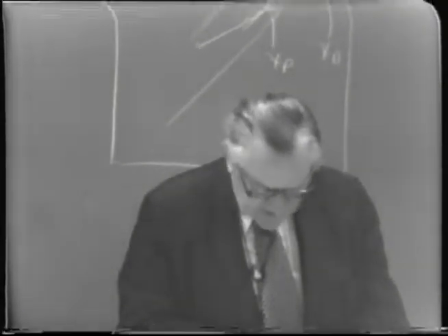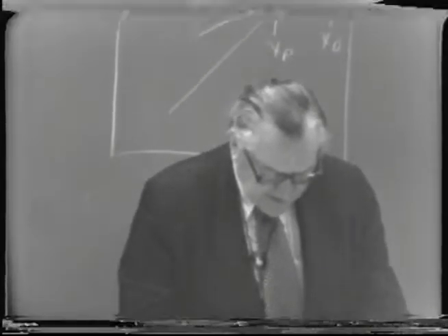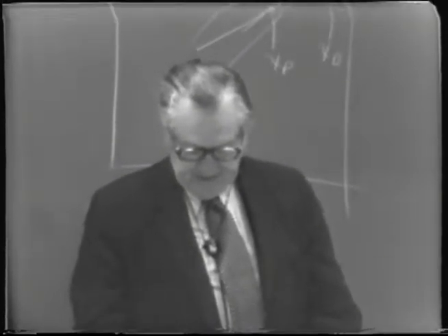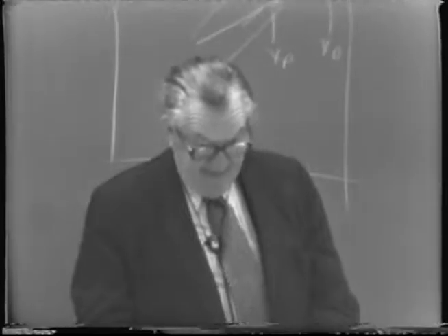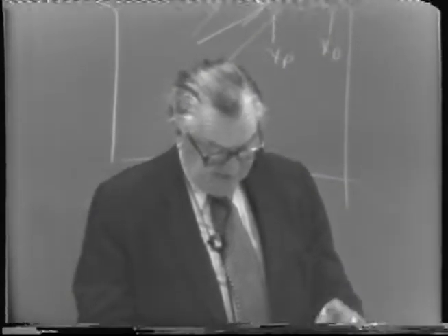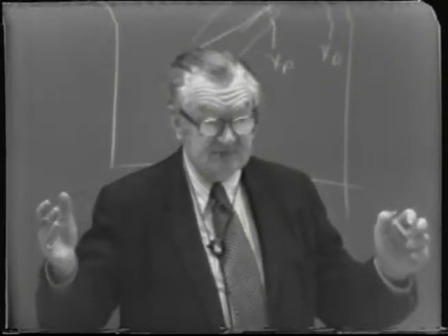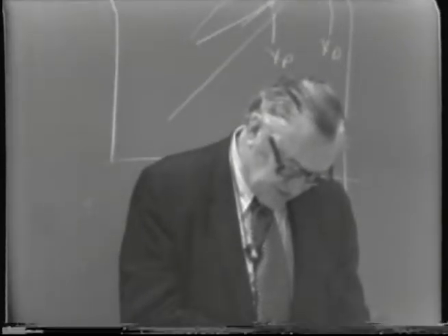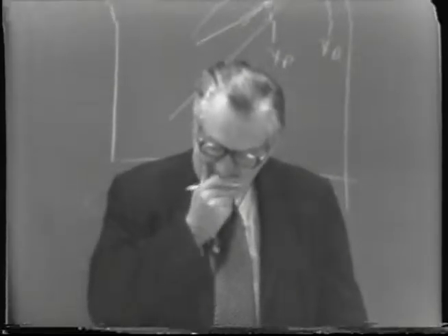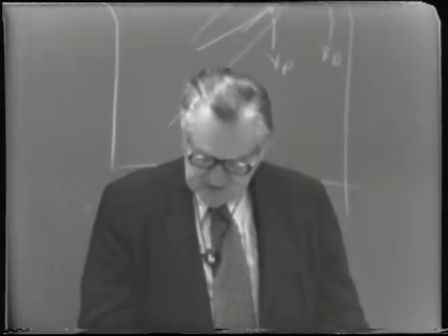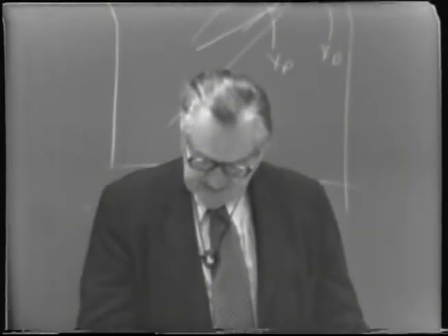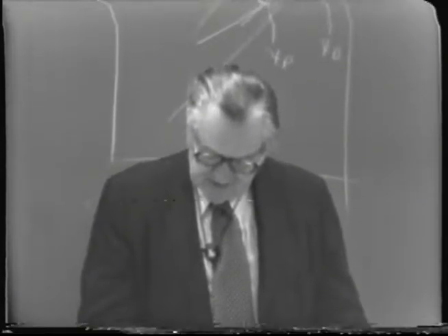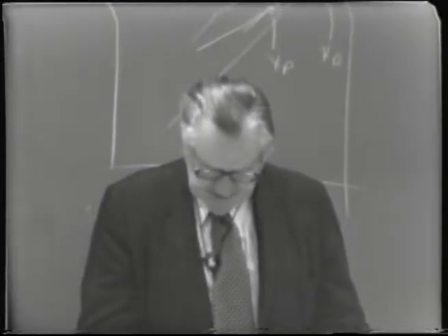So it looks like we required a total of just slightly more than 13 to span the change in liquid composition down to X sub F, or down to the intersection of the Q line with the operating line. Over on the right-hand side of this chart, I've written the number of ideal plates in the concentrating section. Above the side stream it's essentially 4, and below the side stream it's 9 plus a fraction, or about 13 plus.